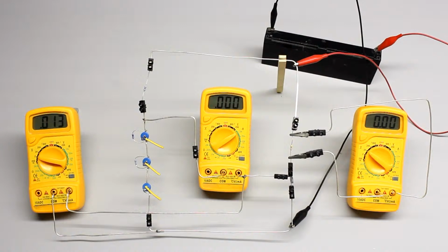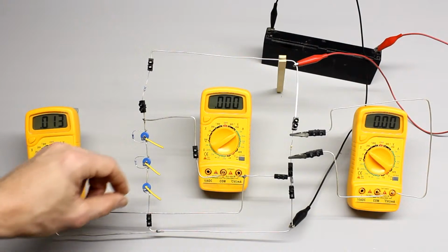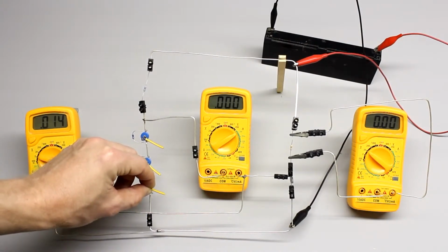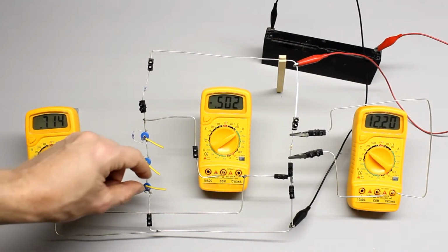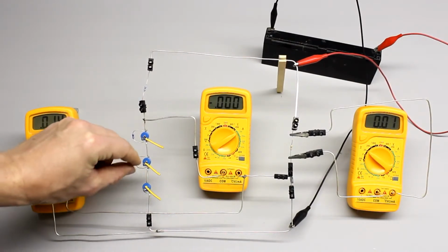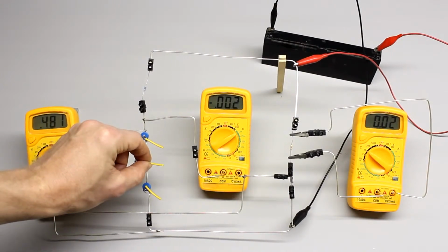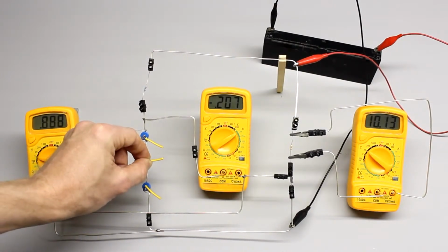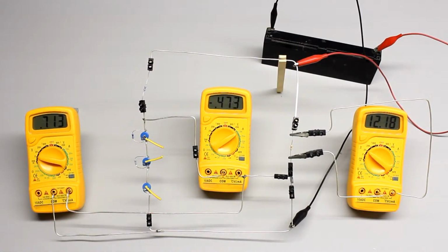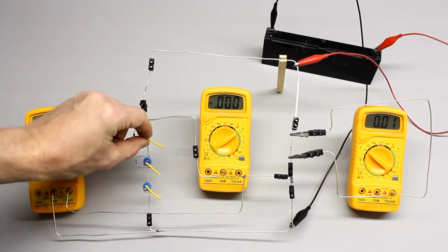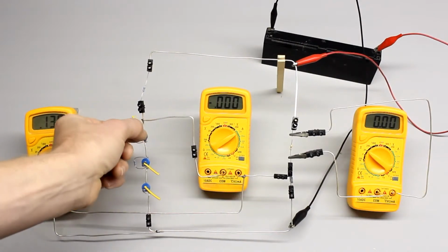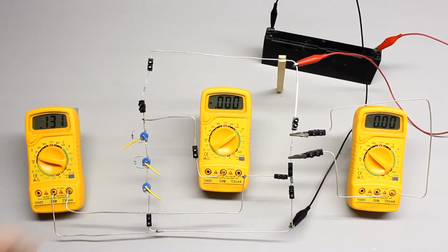No current through the base pin can be detected and the voltage drop at the load resistor is 0. By turning the bottom potentiometer slightly, a current of approximately half a milliampere is running through the base pin and almost all of the battery voltage is detected at the load resistor. A greater angle of rotation is required to get the same effect while using the middle potentiometer, and even the full turn of the top potentiometer is not sufficient to cause that base current.